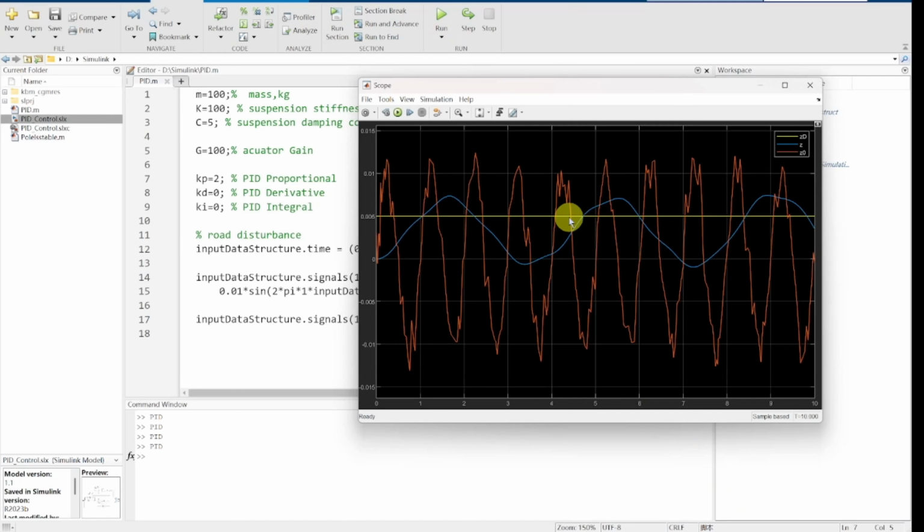Look at the screen. The blue actual curve, which was originally way off, is immediately pulled right up near the yellow target line. The role of P is to fight the current error. Think of it like a spring in a car suspension. The further you deviate from your target, the harder it pulls you back. But a pure spring has a problem. It has no damping, which leads to this severe oscillation.